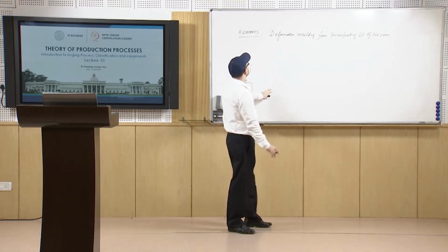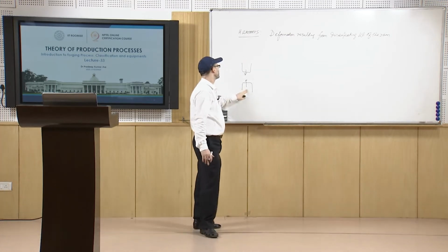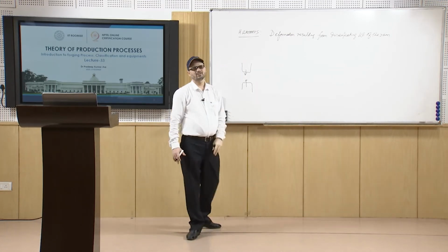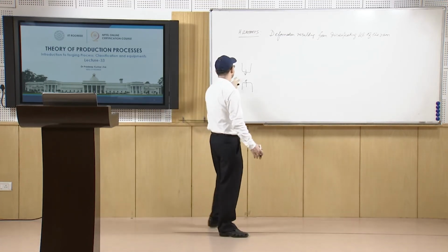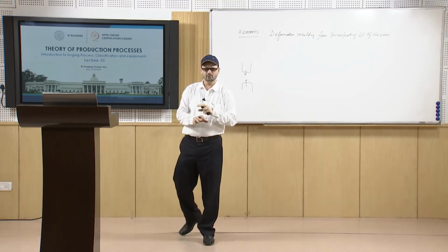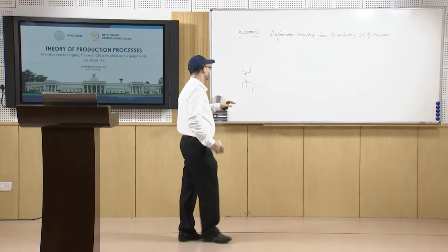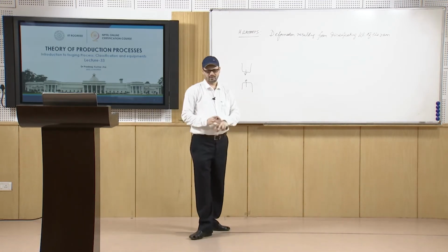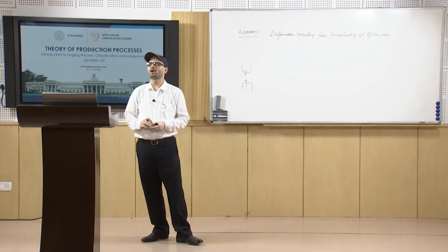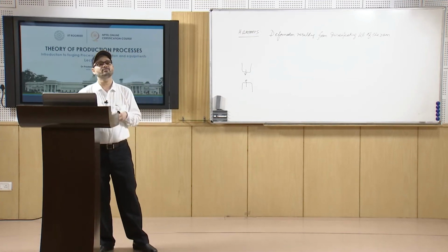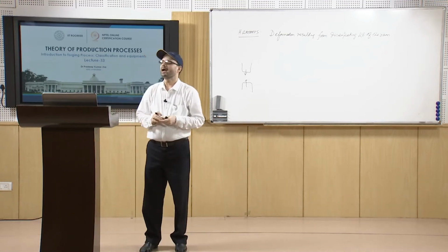So, your vibration is transmitted to the foundation. So, the foundation needs to be very strong. In this case they are meeting at this point. So, that foundation need not be so strong in that case, because it does not transmit the vibration to the earth also. So, you need not have that much of a problem as regards the vibration. So, that is the counter blow hammer, and a velocity of 10 to 30 meters per second is basically achieved for the ram in these counter blow hammers.